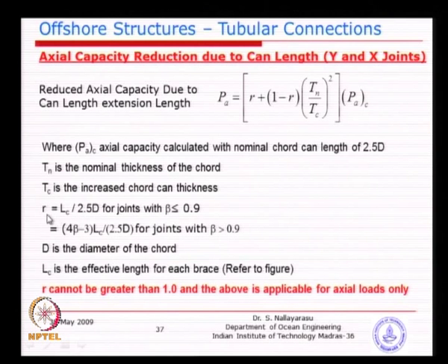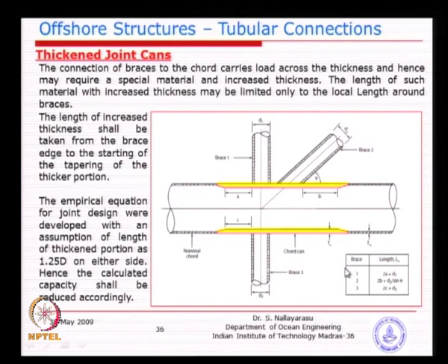So, you look at this R value, this is the LC. LC is nothing but the total length calculated by this arrangement. Basically, you will add this length plus diameter plus this length. So, for this type of joint you have both sides 2c plus diameter for the bottom one. The top one you see here 2a, a is here, one more a can allow here plus the diameter, but for the inclined brace you just divide by the sin theta to get the elliptical footprint. I think most of you understand the geometry.